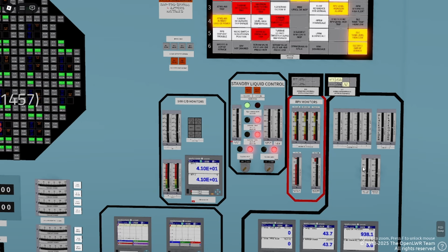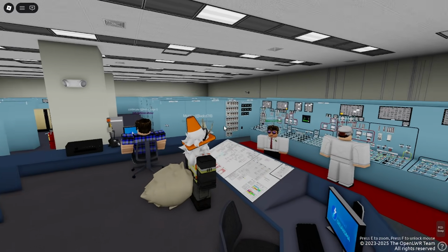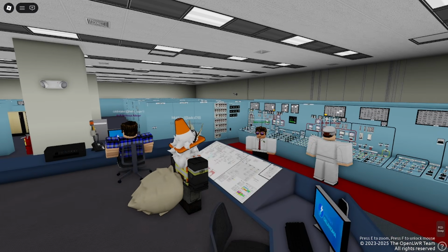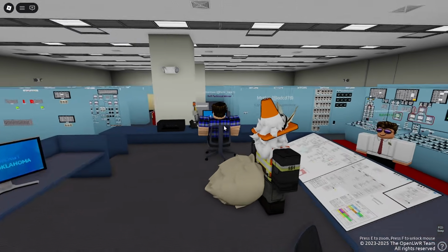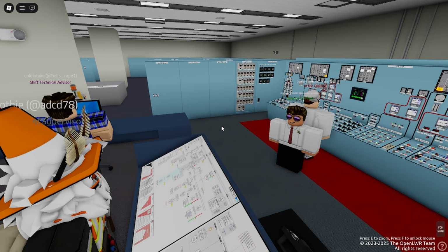BOP, yes. I would like you to start depressurizing the reactor down to 550 psig, not exceeding 50 psig per minute. I understand you want me to lower RPV pressure to 550 pounds, not exceeding 50 pounds per minute. That is correct.